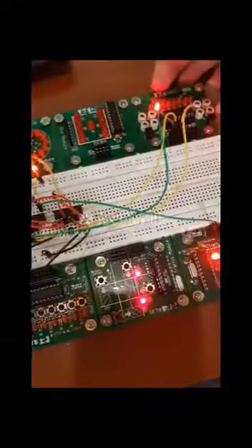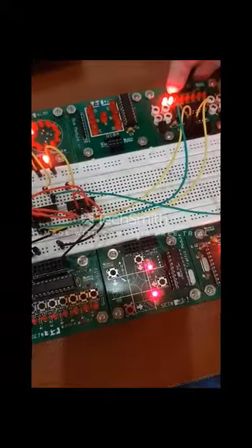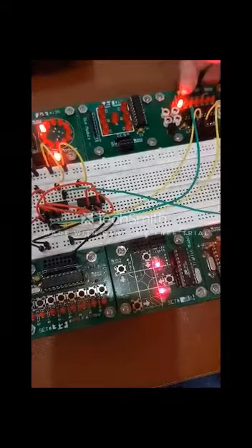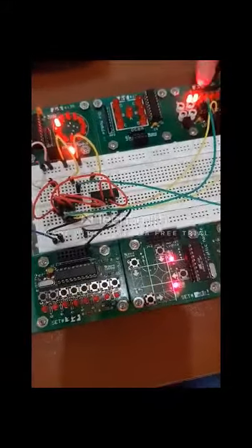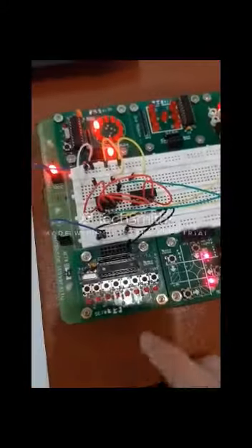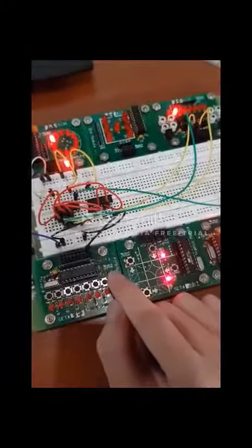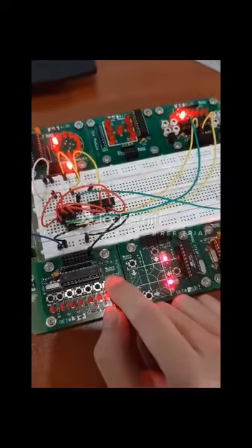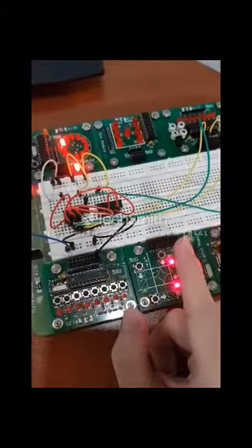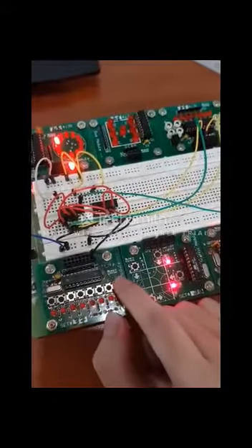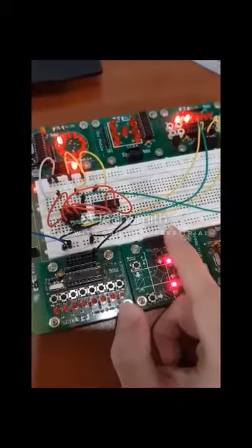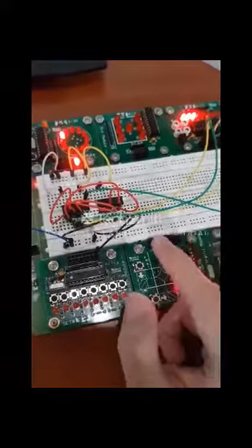As you can see here, it's actually running from 010, 101, 110, 111, 011, 001 to 100, and then back to 010. It loops in this series, and when the button is pushed at 001, it will turn to 000, and it loops in 000. When we press it again, it will loop back to 100, and then start looping in this series again.